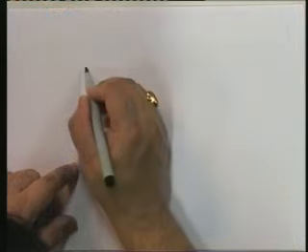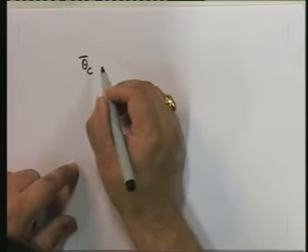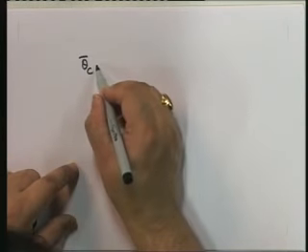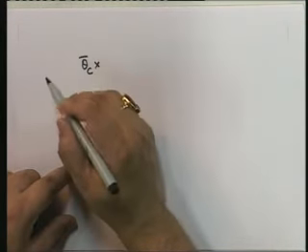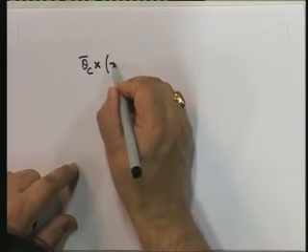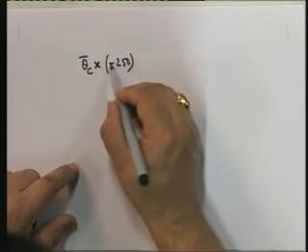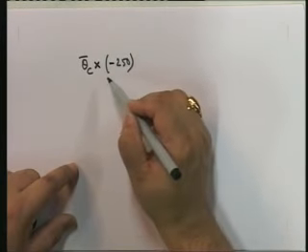Now let me put theta c. Let me put the arbitrary condition that theta c is equal to 1. So then the work done will be theta c, that's the arbitrary, and what is this thing? Theta c is in this direction. So what is the moment at that point? You will see that it's a clockwise moment, so you're going to get 250 into theta c. This is the external virtual work.